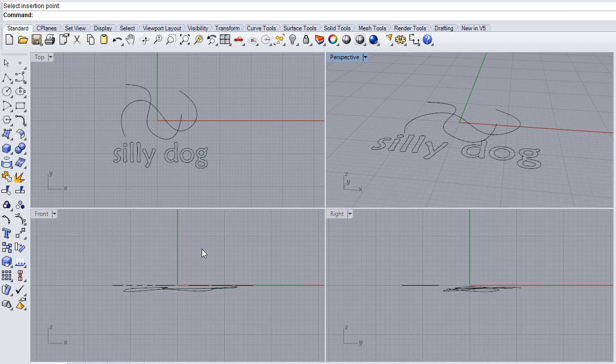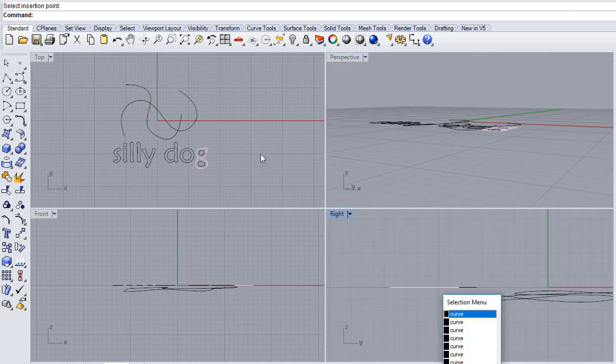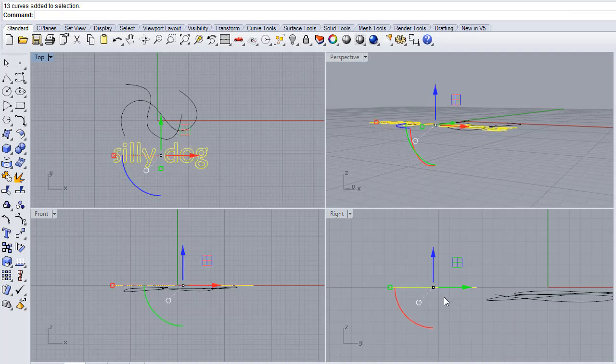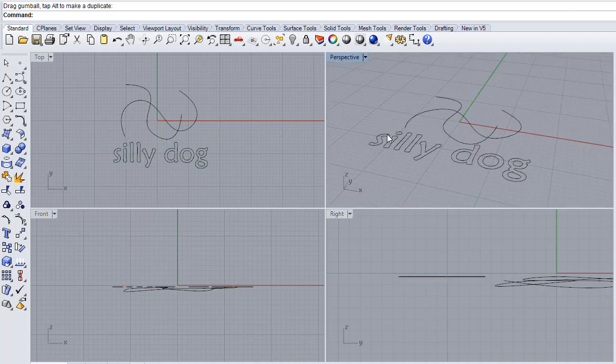Good morning guys, I simplified engraving for you down to a single command, noting that this can only be used for engraving and that your geometry should be in its final position. In other words, if you're engraving at 0, you're not going to engrave anything. If you want to engrave to 0.25 deep, you're going to have to move your engraving down to 0.25. So the cutter tip is going to follow the Z position inside your Rhino.